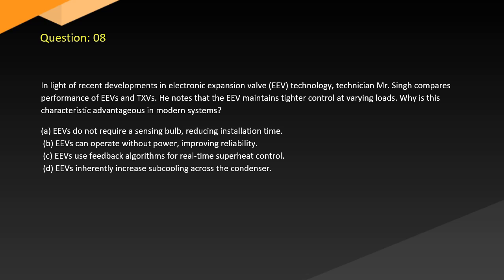A. EEVs do not require a sensing bulb, reducing installation time. B. EEVs can operate without power, improving reliability. C. EEVs use feedback algorithms for real-time superheat control. D. EEVs inherently increase subcooling across the condenser.